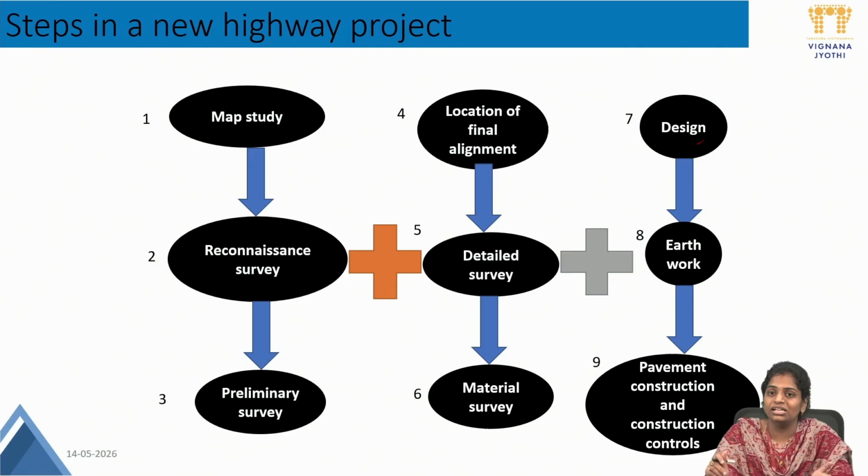Design, what is design? Design of geometric standards, how geometric standards can be designed. What are the side distances, super elevations, everything to construct the road. How many curves are there, how many slopes are there, how much radius the curve should have. For this curve, how much land should be acquired, everything will come under the design.